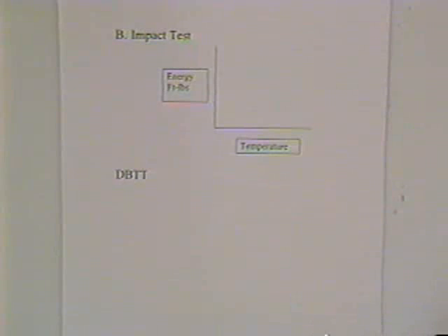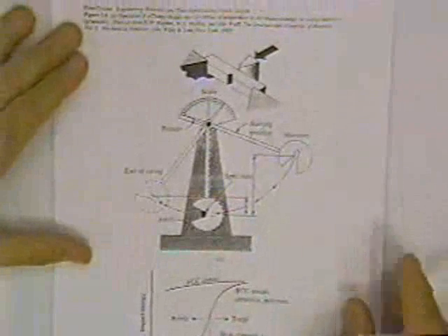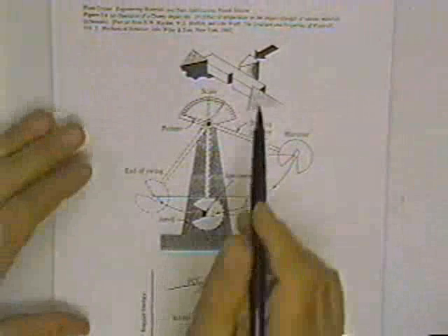And once it crushed into that iceberg, the material behaved in a brittle fashion, so a number of cracks opened, not the 300-foot gash that was first originally thought. Now, for an impact test, if you look on page 33, one of the common impact tests is a Charpy V-notch test.